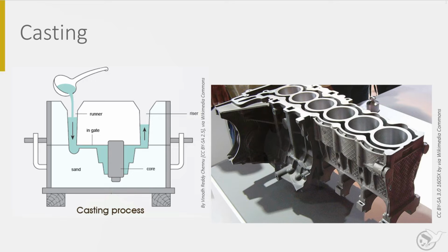After pouring the metal in the die, the metal has to cool down, so the part can be retrieved from the die. Note that shrinkage of the part should be compensated in the die design.